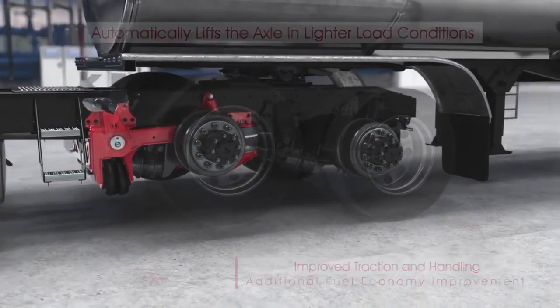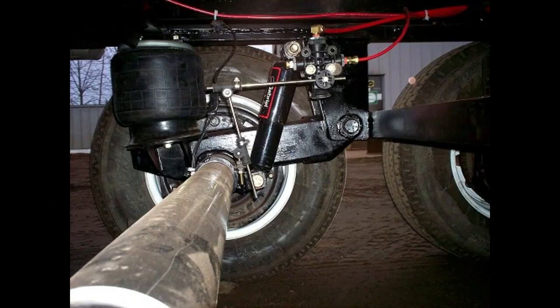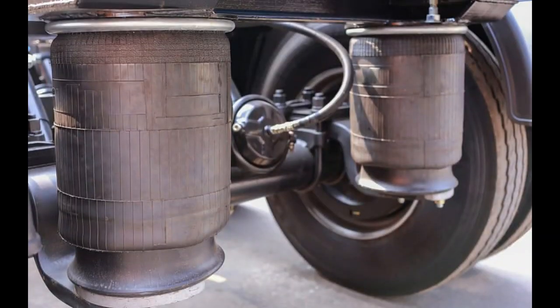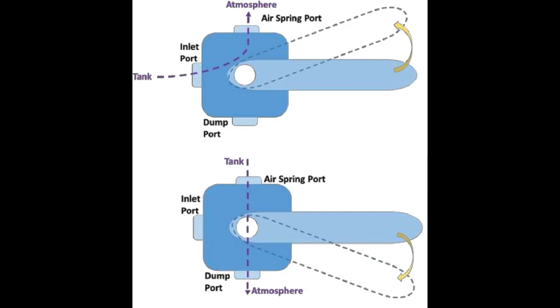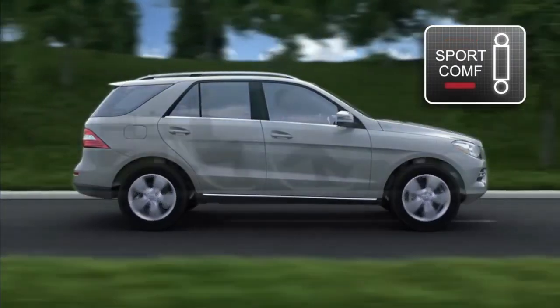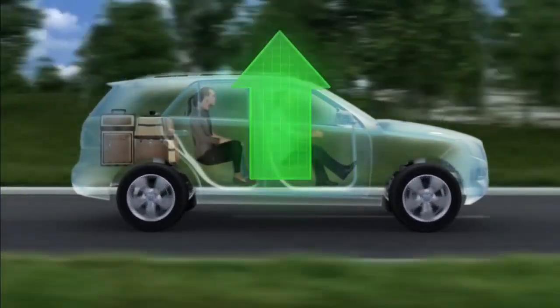Third is the supply line. Supply lines play a vital role in transporting the compressed air to the airbags within the suspension system. These lines closely resemble standard high-pressure airline tubing and are typically routed alongside the vehicle's frame. Supply lines are typically constructed from rubber or polyurethane materials. However, in some cases, custom steel lines can be used as an alternative. These steel lines not only provide a more polished appearance but also offer increased durability and sturdiness.